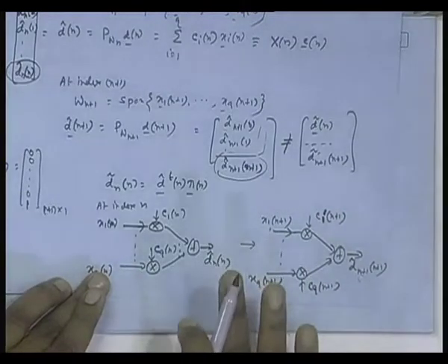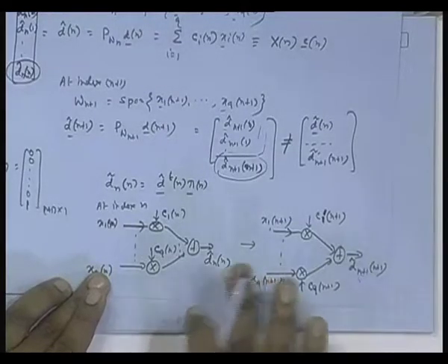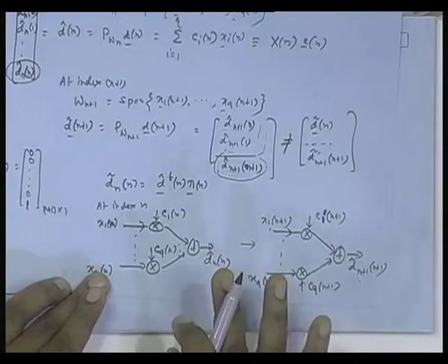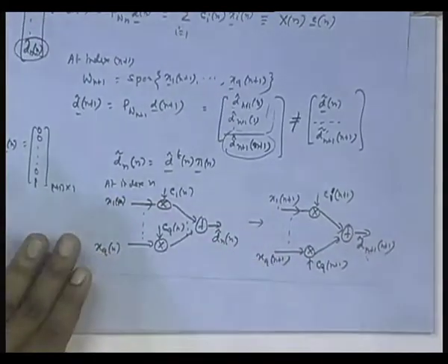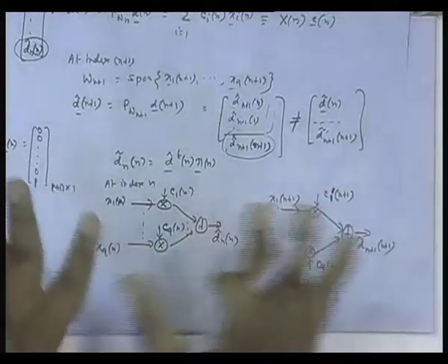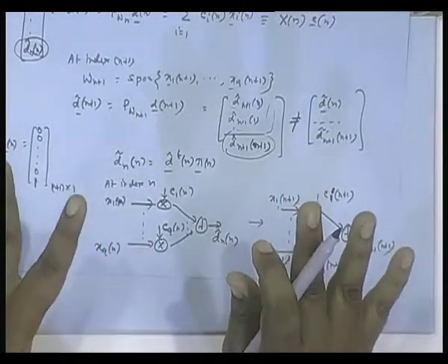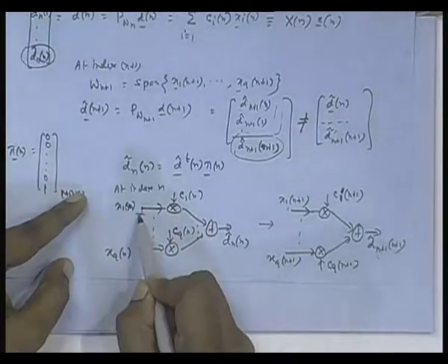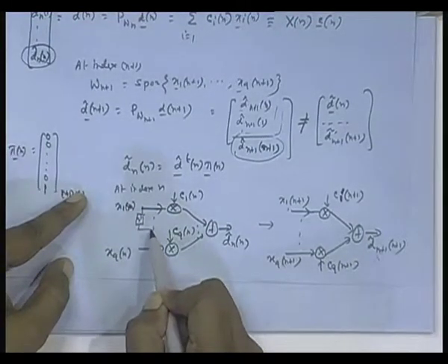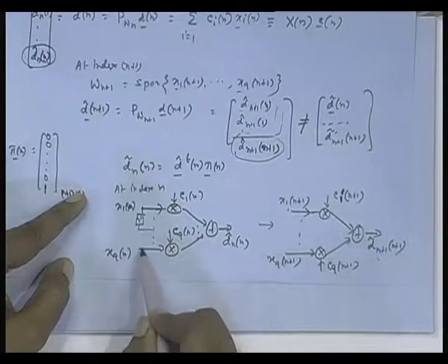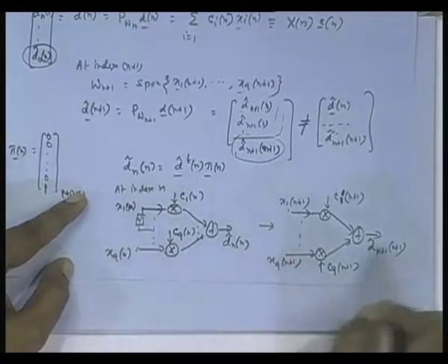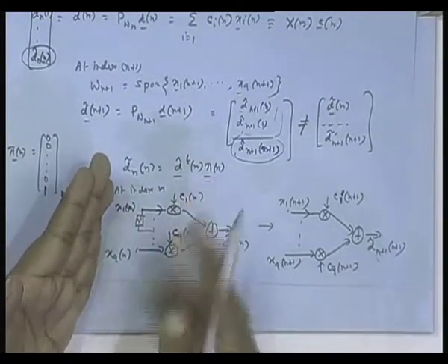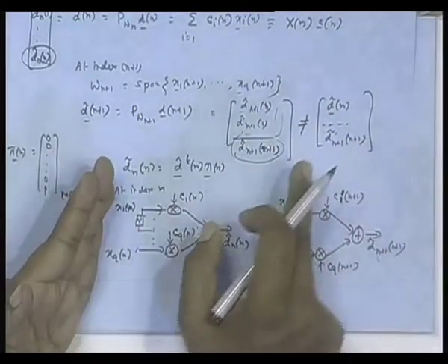This is the schematic, mind you. It will come in an indirect way, because I will be doing linear prediction again and all that, but the basic philosophy is this. You understood the estimation mechanism here. Here it is more general. If it is a filter, x1n, there would be a delay here, then x2n, there will be a delay here, x3n dot dot dot, and finally a delay in this. Same here, then it becomes a FIR filter. Coefficients will be adapted by that recursive least square algorithm to the new set.